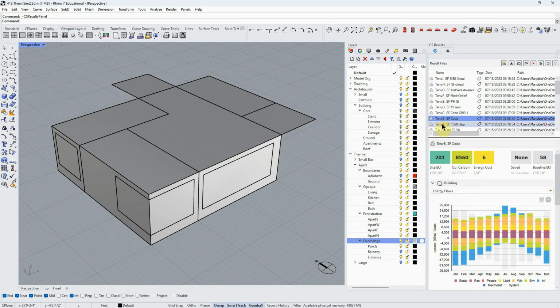If I go back to the first one, remember we're at 0 here, and above that is heat gains, below that is heat losses, and the really light gray is the mechanical system adding, because the heat losses and the gains have to balance out. That's the whole point: if we lose a bunch of energy in our envelope, we're going to add it with the HVAC heating system. That's the basic idea of this graph.